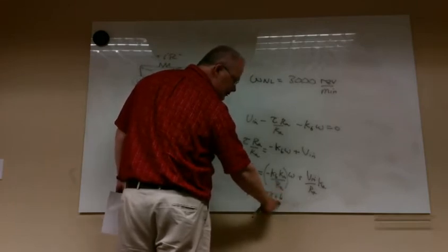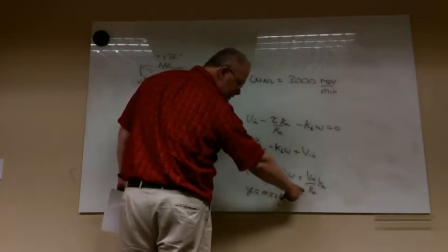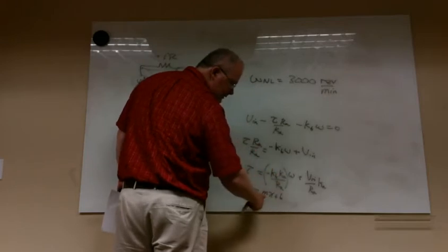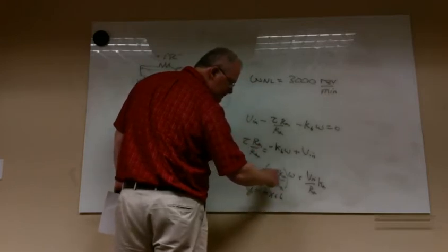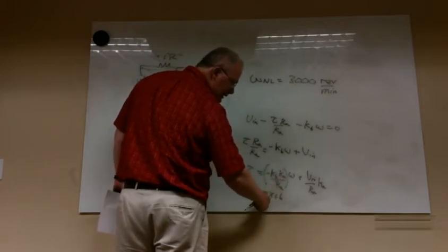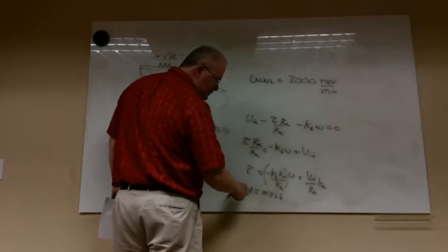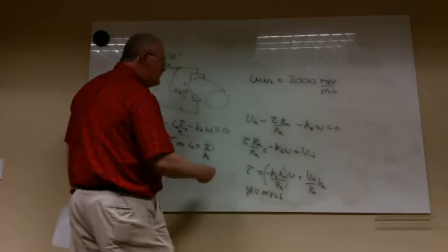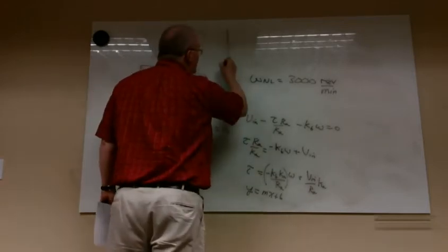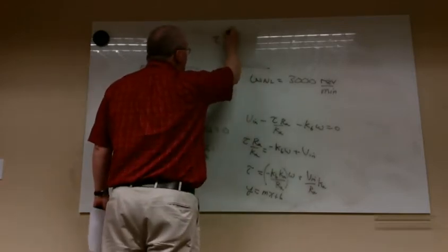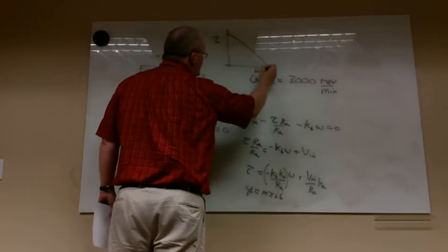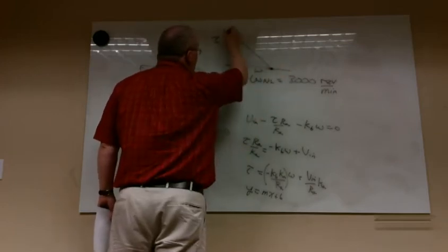The y-intercept is the stall torque that I just told you about. This is the slope, a negative Kb Ka over Ra. X is the independent variable of speed as you move up and down, and then torque is what we're going to get out. So that gives us this curve that you see there, torque versus omega, like this. And we get these two operating points.